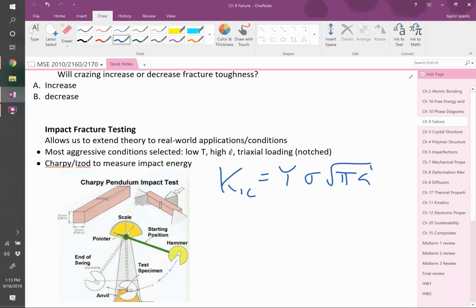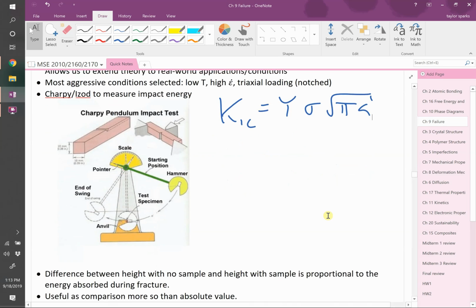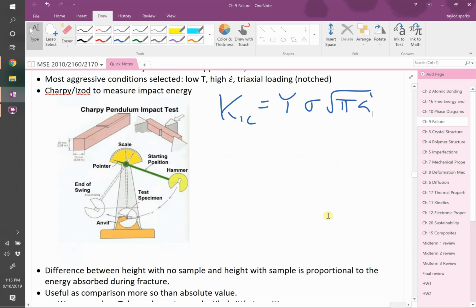If you do it right, you'll pop that right along where you scribed it, which is a pretty handy tool. So yeah, that's exactly right. Okay? So this is not that, but this is kind of that same idea. You're making it fracture in a single spot because you're putting a big flaw right there. So what they do is they take this bar, they lay it across two supports, and then they've got this beam that comes flying in and bends it, right? And the tensile end is over here. So it puts that notch under tensile stress, and it's going to cause it to break.